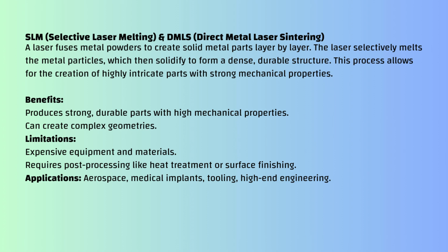These technologies can print parts using titanium, stainless steel, aluminum, and nickel-based alloys. They are essential in aerospace, defense, and medical industries for parts like engine components, implants, and heat exchangers. While powerful, they demand post-processing such as support removal, stress relief, and surface smoothing.